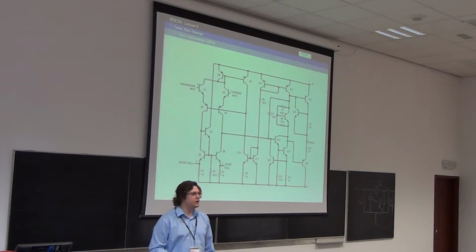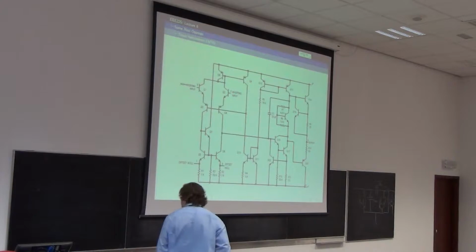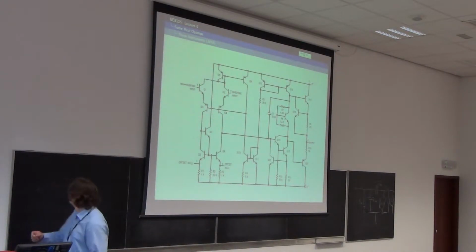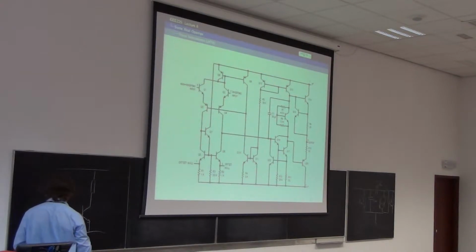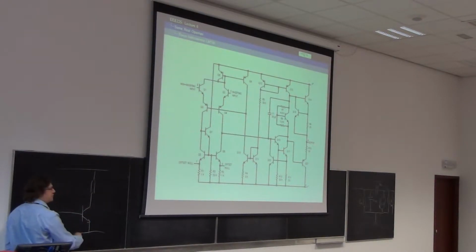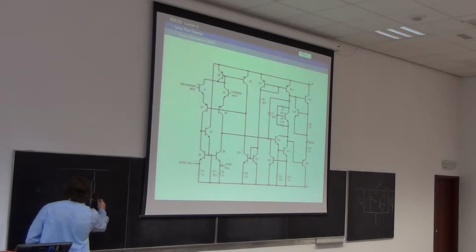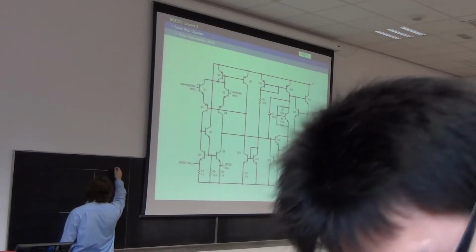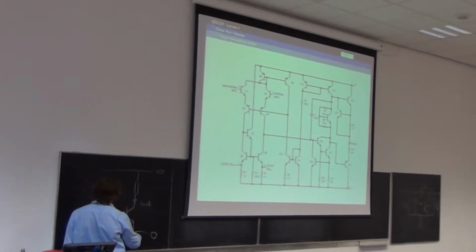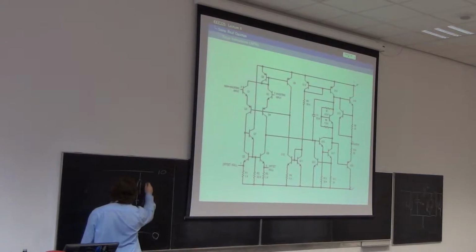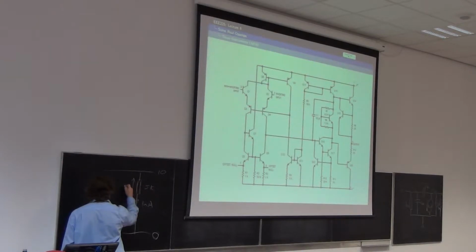Alternatively, do it for a common emitter amplifier. In the situation where you have just a resistor, let's assume a quiescent current of, I don't know, a milliamp, and if we made that 10 volts and now 0 volts, we'd have, oh, I have to have a resistor as well, won't we? What should we make the resistor? Let's make it 5k. So we'll have 5 volts across there.